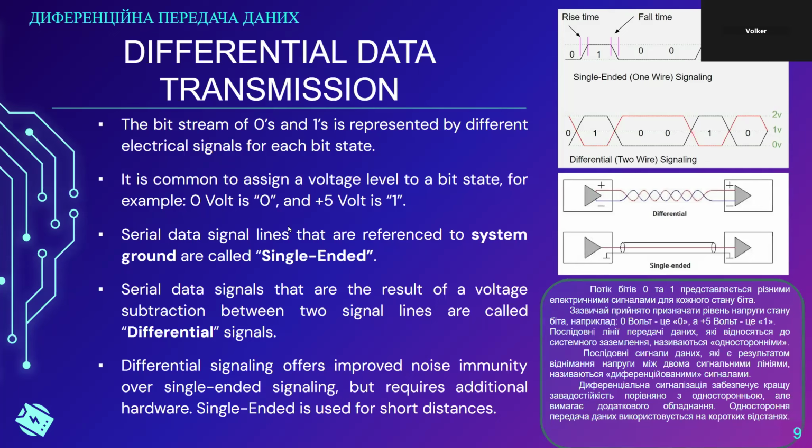So that is the difference between on-circuit-board and off-circuit-board systems. What is happening here is that the differential signal is subtracting. It needs a wire pair, so it needs one extra wire over a single-ended connection. But any kind of noise that is impacting the connection shows up on both of these wires in the same polarity.